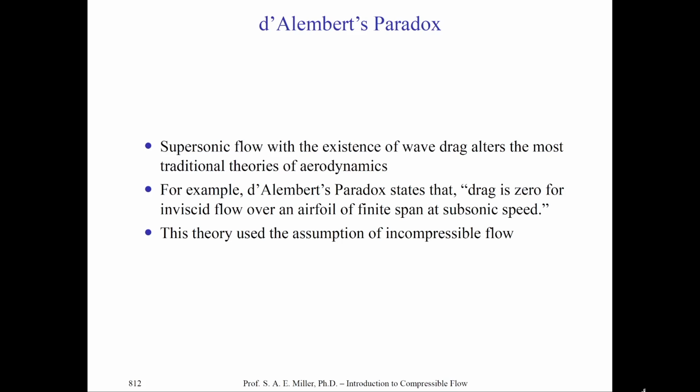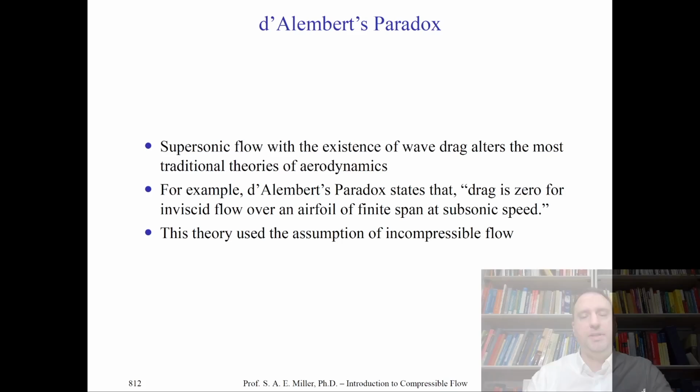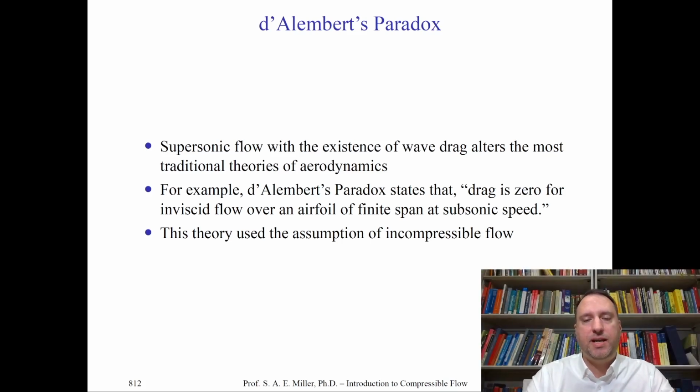Let's continue and discuss the idea of D'Alembert's paradox. In previous classes, you learned the D'Alembert paradox applies to inviscid, incompressible flows over bodies where there's no drag. Now, if we have compressibility and high-speed flows, of course, shock waves appear. So supersonic flow, with the existence of so-called wave drag, which we just introduced, will alter the most traditional theories of aerodynamics, and help us alleviate the strange D'Alembert paradox.